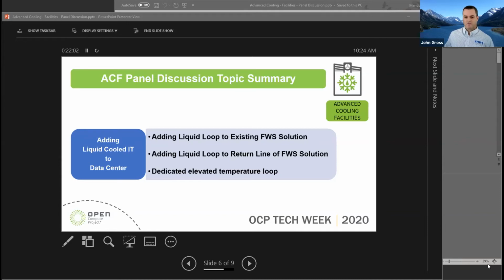And there was some confessions made by some folks in the voting members group that 27C was picked for W2 mainly because most of the ITE manufacturers were hanging out at about 27C at the time that classification was created. But yeah, the goal also right now with the renaming is to make it simpler and easier for folks if classes are added or taken away.